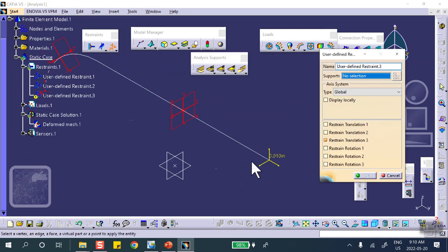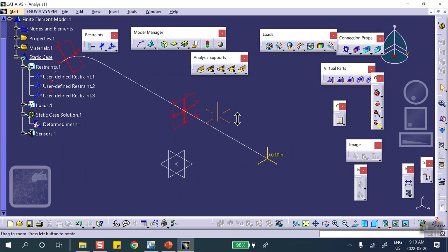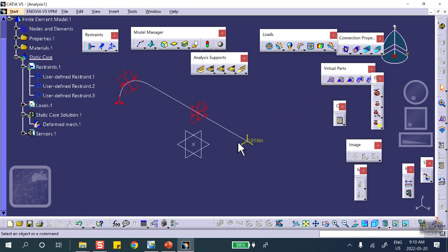This point, no displacement in the direction X. That bottom point can move though. That bottom point can actually move. Okay, that's the problem. This is not going to do it, because this point can in fact move in that plane because of the symmetry that we put in there.